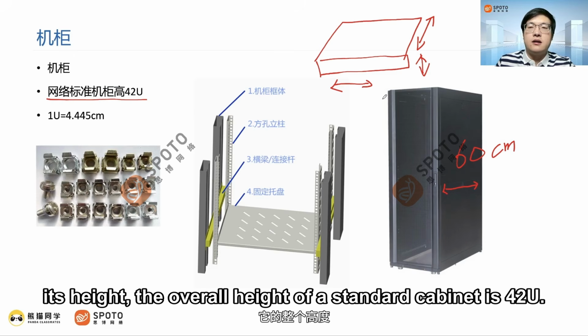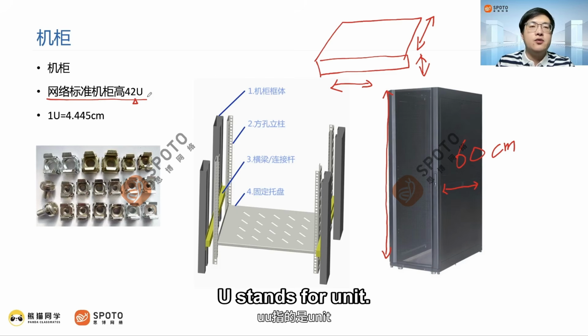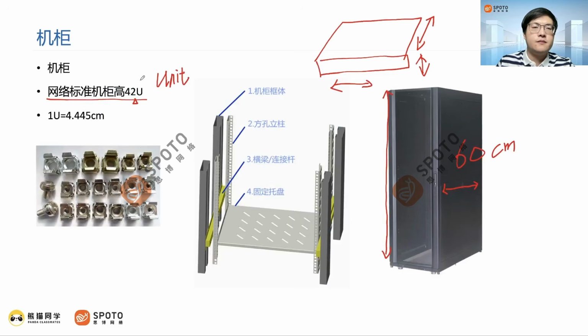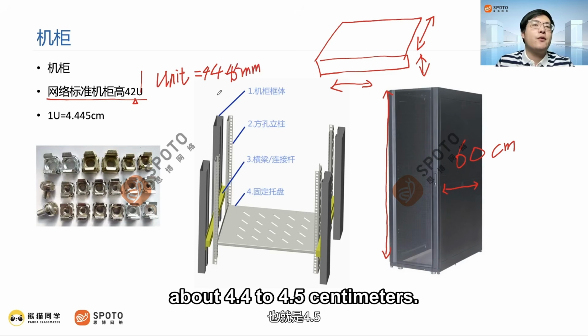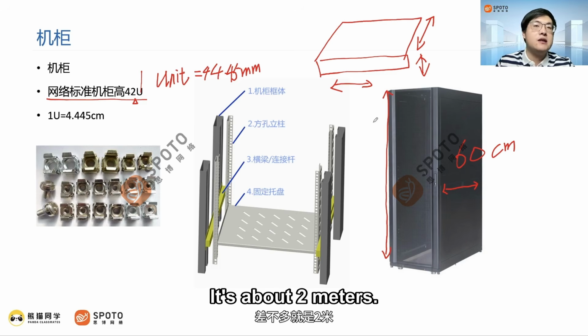And then, its height. The overall height of a standard cabinet is 42 U. This is the standard terminology for our cabinets. U stands for unit. One unit is 45 millimeters, which is about 4.4 to 4.5 centimeters. That's 1 U. So 42 U, you can multiply it yourself. It's about 2 meters.